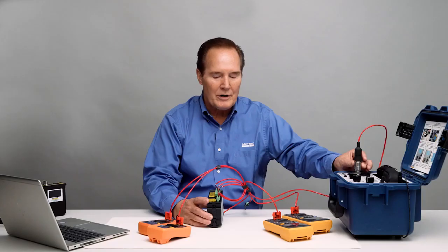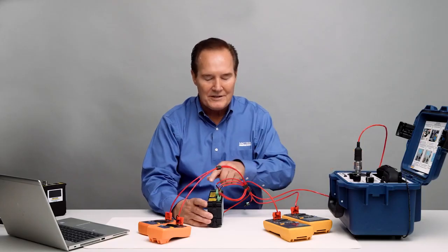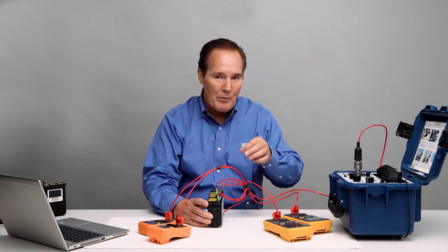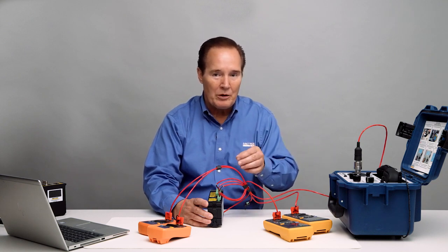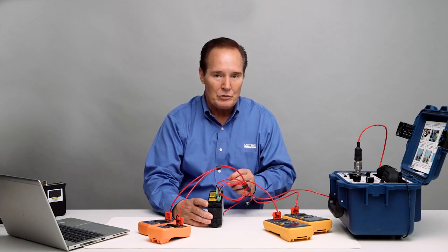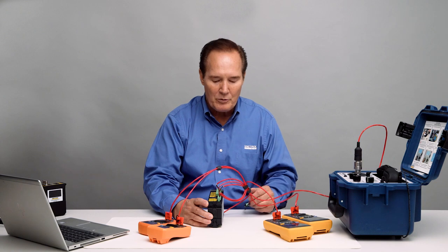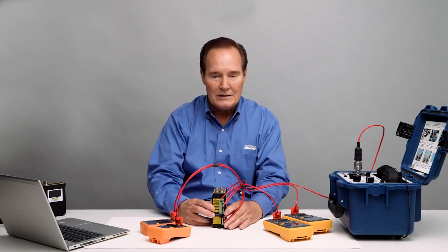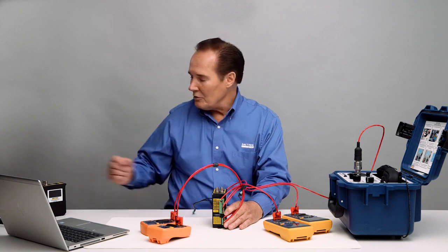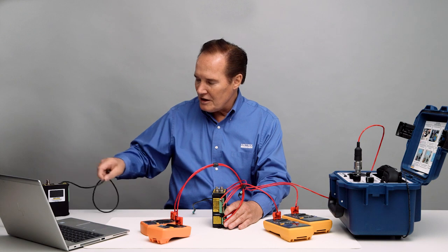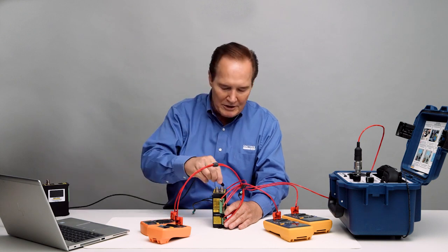What we're going to do is bring it into channel 1 as I've shown you already. And then we're going to have output of acceleration out of channel 1, but integrated velocity output out of channel 2. And so that's how we're going to set up our software. So in order to do that, I've got to connect the 5580 to our software. And I'll do this using this cable. It's just a mini USB to USB connection.